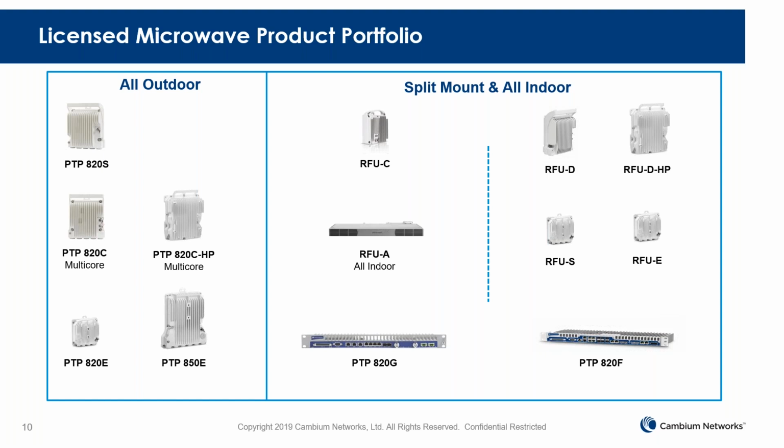Hey, Alan. I think so. The main thing I would suggest is if you are using the same frequency, you would want to be spatially at least 5 to 10 feet away from your original source. This again, as you mentioned, depends on the type of antenna you have.